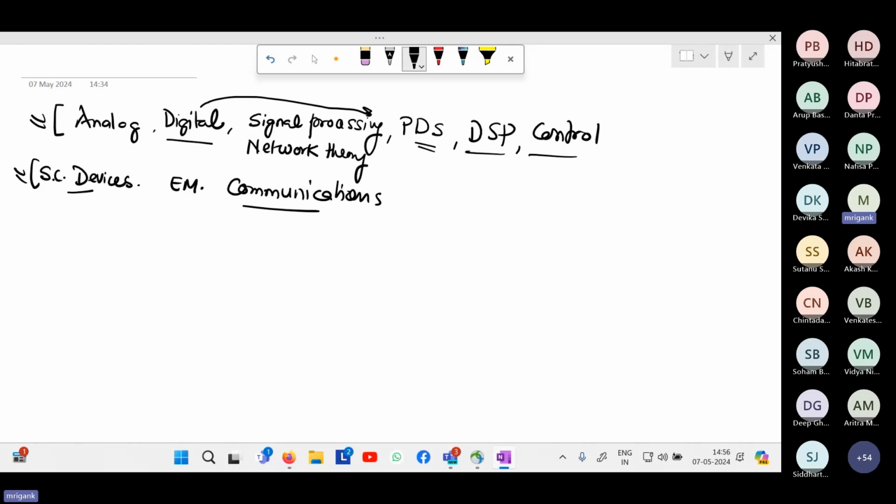So all these communication circuits may have optical communication also, like the example that I took in that transmitter receiver circuit, which had a receiver block based on the common gate circuit, and it has a photodiode. There, ultimately, the assumption is that the communication is happening in the optical mode. So the optical signal comes and it can produce a current in the photodiode, and that current can be received and amplified by the common gate circuit.